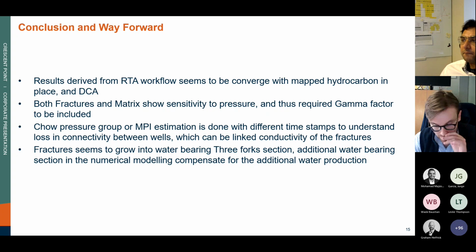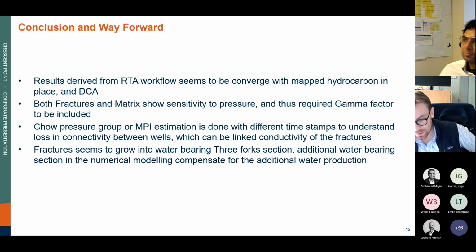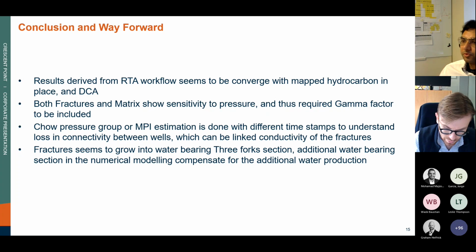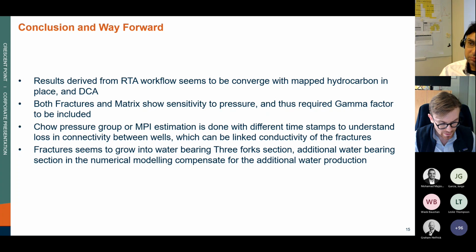I'll start from the top with Rohit's question about whether you're able to distinguish between flowback and frac water and the formation water in your model. How do you actually do that in practice? First of all, we have a continuous composition or water analysis being done, and based on the difference in salinity, we get to know how much of the frac water and the formation water is coming along. Also, of course, volumetrics is there. So based on both composition and volumetrics, we are trying to get that.